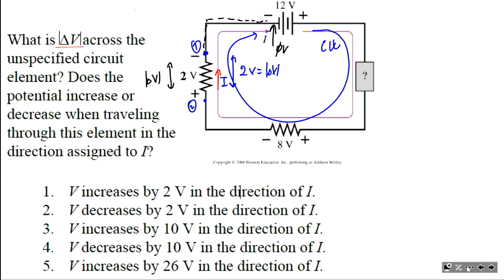Because again, we know electric current always points from a higher potential to a lower potential, which means if we know direction of electric current, we can use it backwards. We can figure out which point has a higher potential, which point has a lower potential. So, 0 volts, 0 plus 2, 2 volts. That's a potential. And this potential does not change up to here. And now electric current through the second resistor points to the left. And against electric current, potential rises from 2 by 8.